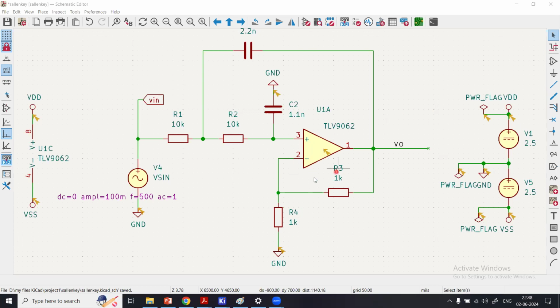So here you can see that the operational amplifier has been configured using negative feedback by means of resistors R3 and R4. We configured this operational amplifier in a non-inverting amplifier mode, and then we have got R1, R2, C1 and C2 to provide the filtering network of impedances. Together, this circuit acts as a second order active Sallen-key low pass filter with an amplification gain.